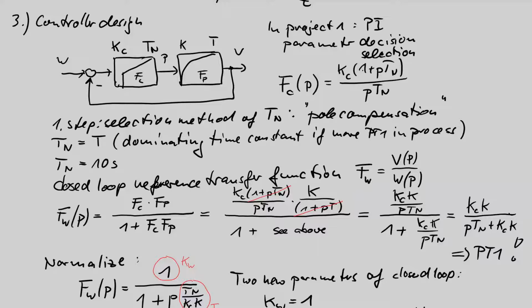Also, you should do this in the analysis of your closed loop system. What happens with your actuator value? That is, I think, the very important internal step. What you have to do after design: check your actuator values, because this gives real information. Is this realizable? Do we want to have this? Is it a load for your motor?